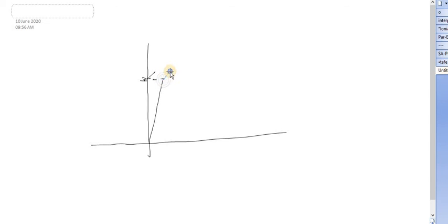It is very difficult to find this particular value, but we need to know the stress corresponding to the limit of proportionality. So what we do to eliminate all the difficulties, we don't rely on the instrument, we simply test it. Okay, during the test we know after this point it curves, then yield comes, then strain hardening comes, then the ultimate point is reached, then it collapses.